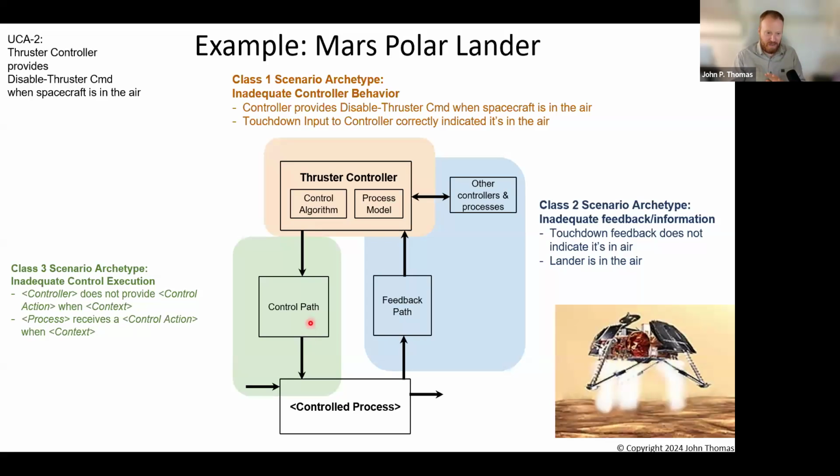But it would remember the request indefinitely. And if you came down to 40 meters, 120 feet, and this had previously sent the request at 1,000 feet, down at 40 meters the thruster controller is actually doing the right thing, is no longer saying shut off descent thrusters because it's no longer getting the vibration signal. So the thruster controller now is actually doing the okay thing. We're at 40 meters and everything's good.